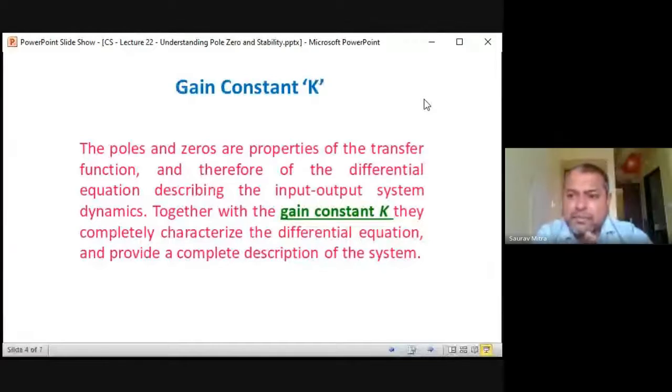That is the characteristic: when the poles are on the left half, the system response will also oscillate, but it will be a decreasing oscillation. But if the poles are on the j omega axis, say for K equal to 20, the system response will be oscillatory with sustained oscillation, because we have seen that a pole pair on the j omega axis produces a sustained oscillation. Now you are increasing the value of K beyond 20. Till K was 0 to 19, the poles were in the left half, but they were shifting towards the j omega axis.